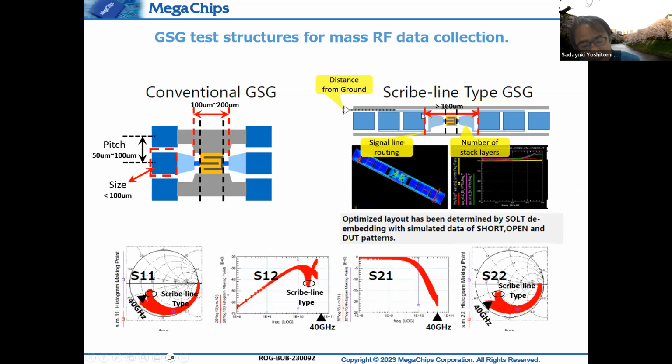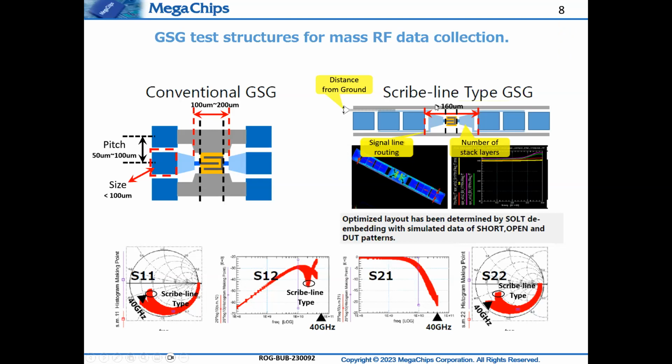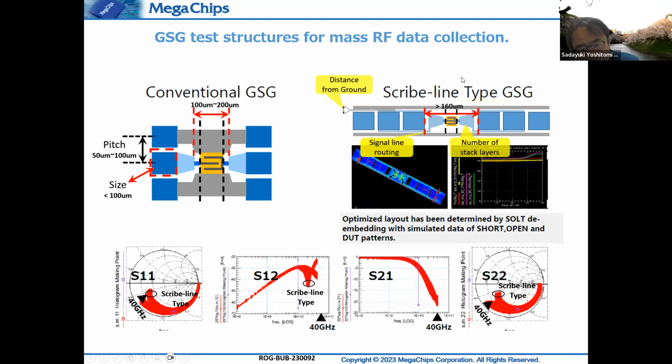So there is an interference because the GSG test probe has an insulating layer like this, here and here. And if we reduce this number down to 160 microns, it is not possible to place a GSG probe in these east to west directions. So from my experience, to keep 160 micron is a safe number.